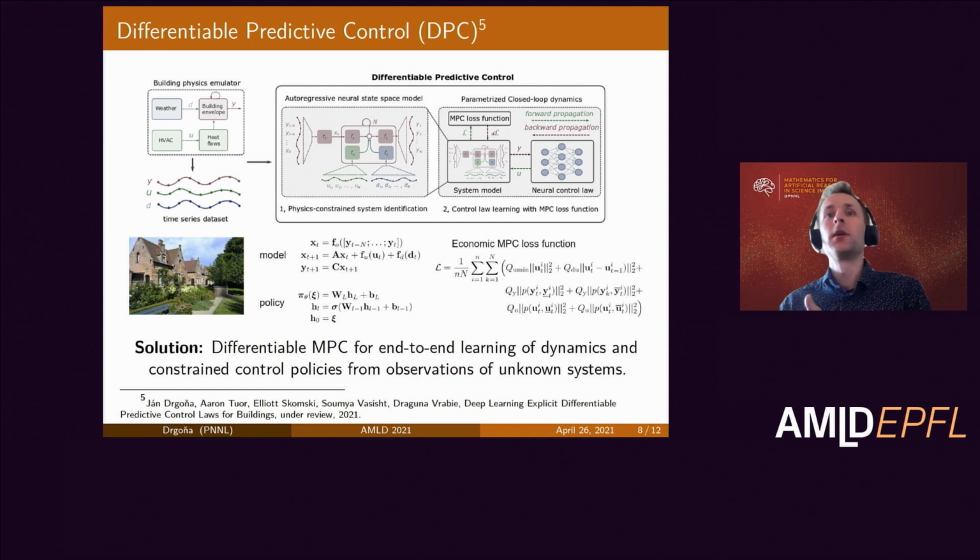That's why we can use it as a part of the closed loop dynamic system with neural control policy, and use a designed model predictive control loss function, which allows us to optimize this neural network by automatic differentiation. And we can simulate this offline over the distribution of desired scenarios, references, disturbances, and potential scenarios which may happen in the real world.